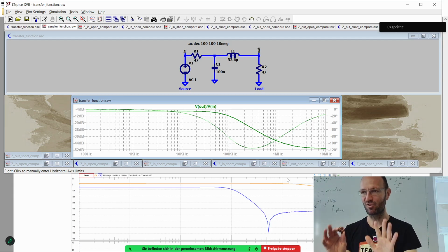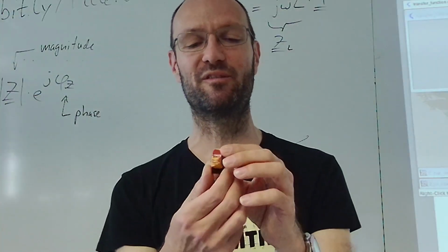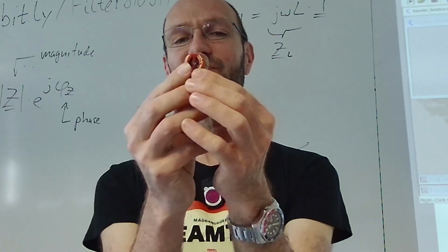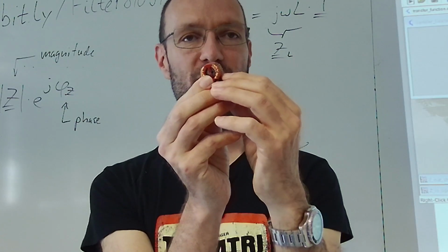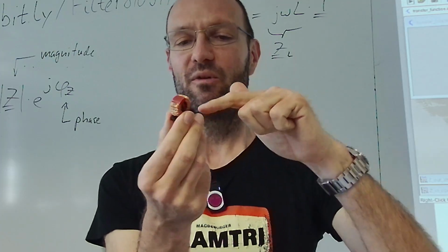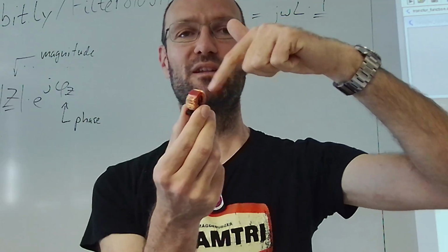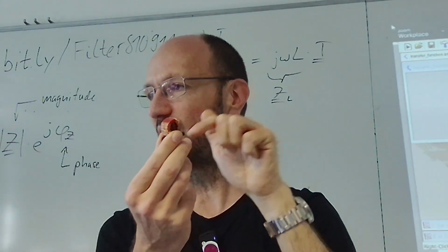Yeah, some electromagnetic interference is, I mean, the filter is there to avoid electromagnetic interference, but if you look at this inductor, it's made out of lots of wires, and there will be a parasitic stray capacitance between these wires. So at high frequencies, in this upper kilohertz, 100 kilohertz, megahertz range, it's very challenging for the current to go all along the windings and create a magnetic field in the core.